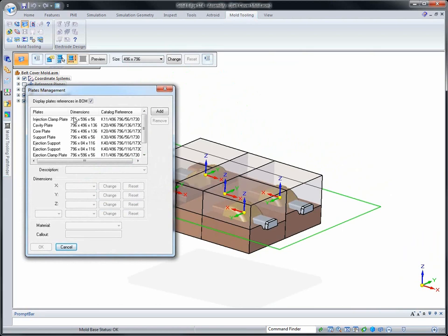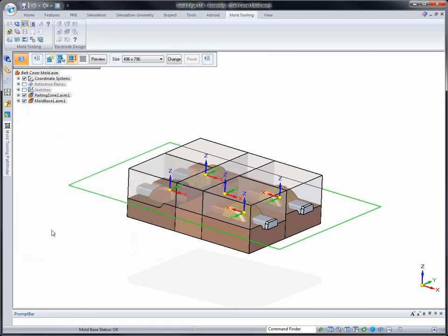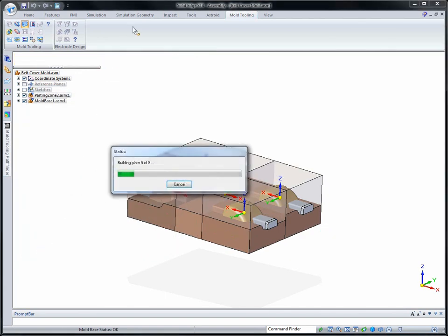The next thing we're going to do is define the standard plate thicknesses. So I made it 77 millimeters because I know the standard plate thickness is 76, and I want it to poke out through the parting surface by 1 millimeter. Now on the bottom side we're actually going to have blind pockets, so we're going to make that a little bit thicker. We need the blind pockets so that we can again have an area to mount our slide mechanism.